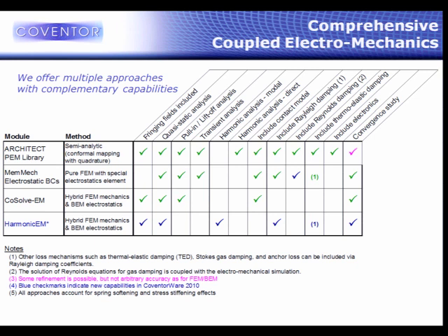You can do some amount of tuning of the models, and we've done a lot of verification of these tools, but ultimately, when you use these tools, you have to go and do some finite element analysis to verify what you've done. The tool still has value because of its capability and because it runs so fast. When you look at the finite element tools like MEMMECH with electrostatic elements, that has less capability. On the other hand, you do have this ability to do a convergence study so that if you keep refining the mesh, you can be sure you're getting a correct answer.